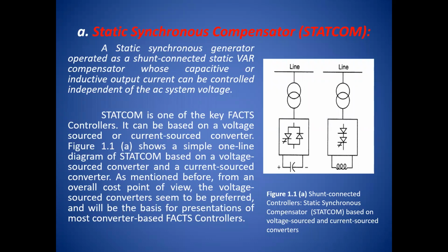In the previous lecture, a basic symbol and classification of FACTS controllers has been discussed. Now today we are going to discuss the static synchronous compensator, that is, the STATCOM. The static synchronous compensator is defined as a static synchronous generator operated as a shunt connected static VAR compensator whose capacitive or inductive output current can be controlled independent of the AC supply.